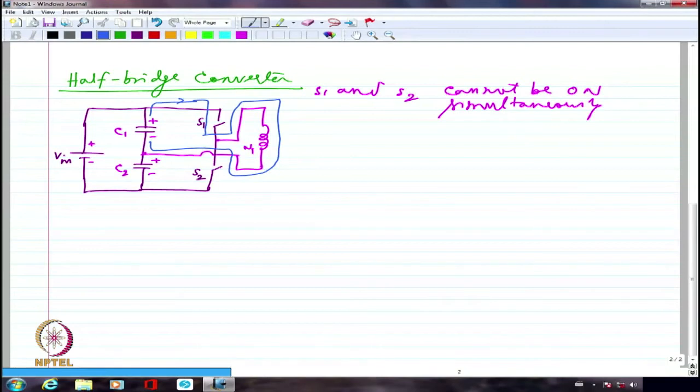So sometimes we face the problem of a voltage imbalance between C1 and C2. But if we choose a sufficiently large switching frequency, then we would not see this much, because the time constant involved will be quite large, because the capacitance values are normally large, because of which the imbalance will not be noticed so much normally.